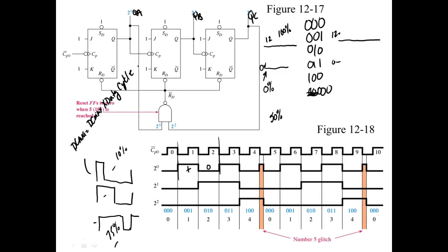This is the preferred method that we use now to control the speed of a DC motor. This is called pulse width modulation. You can research this, PWM. This is the way we digitally control DC motors.